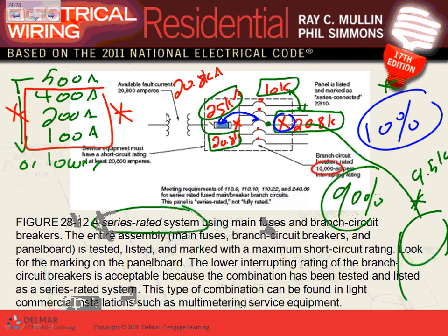The difference between a 25 kiloamp circuit breaker and a 20 amp, 10 kiloamp circuit breaker could be 50% extra on the 25. The price is high because they have to design the magnetic circuits differently, more robust, and so forth. So series rated, cheaper equipment, is used mostly on lighting panels and receptacle panels. 400 amp or less is commonly used. You can get them all the way up to 500 even.